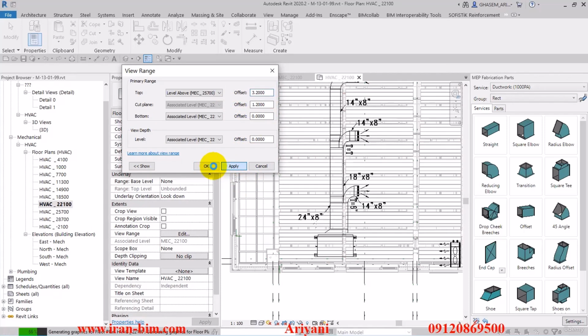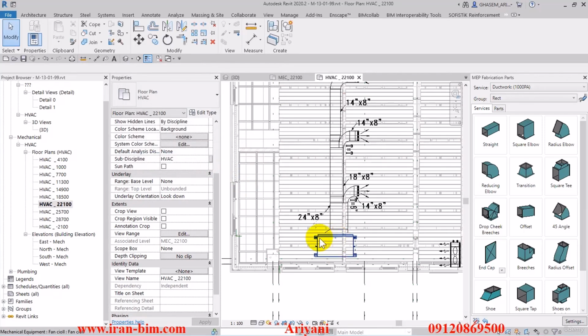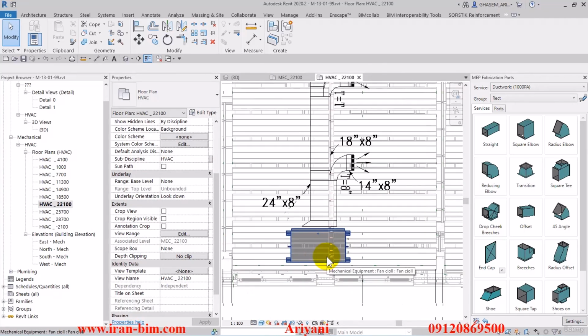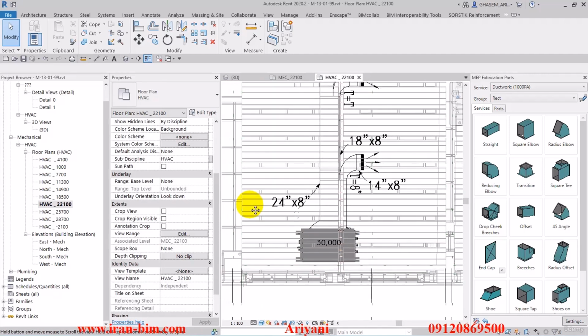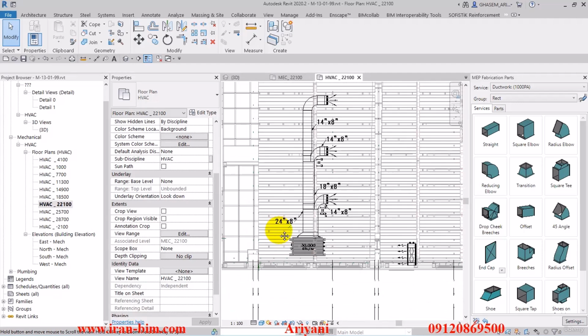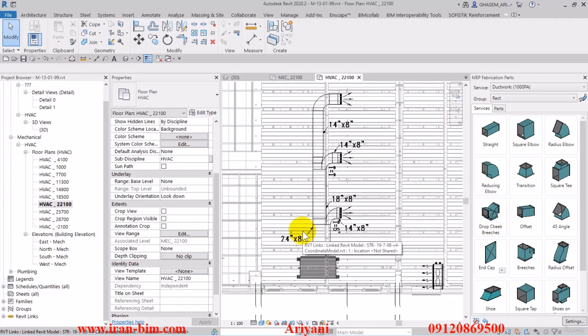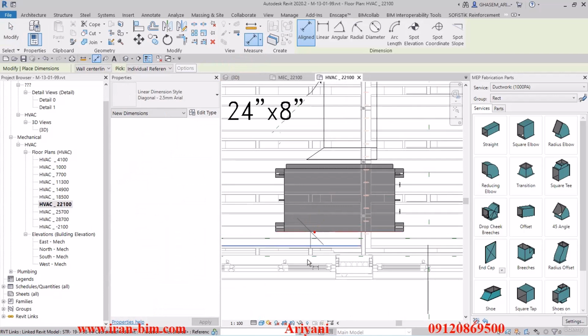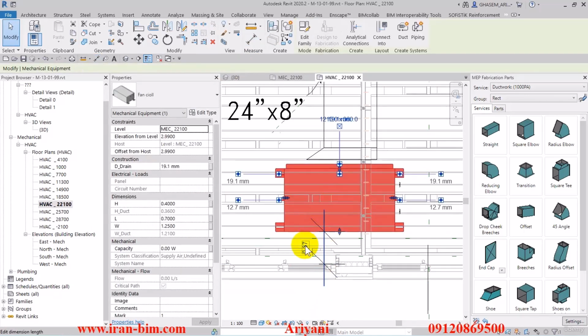Okay, then after that, we can put the plan on shaded settings so that we can see this part more easily. And all right, this is the view that we get. So now we can select the measure tool and put a measuring over here from the edge to the wall and put it fixed on 0.3 so that we'll be able to control it.